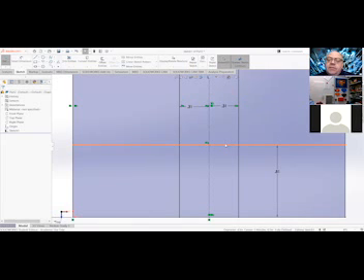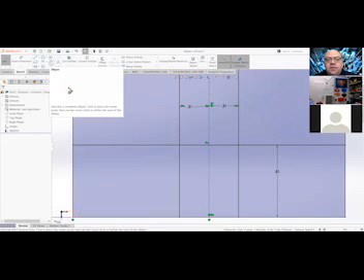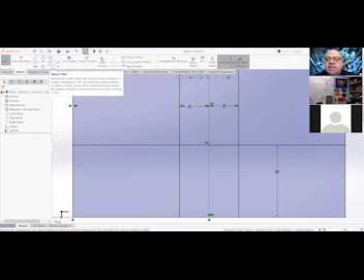Because if I've got all the information, why am I adding more to my drawing than what I need? If you come over to your drawing area, underneath the ellipse is the sketch fillet. This works just like the fillet in AutoCAD. So we go ahead and select. Now, if you hit the down arrow, there's a chamfer. And a chamfer is a little different. It's just a beveled edge to something, whereas a fillet rounds the edge. Both of those are kind of similar, but I want you to make sure you're on fillet.